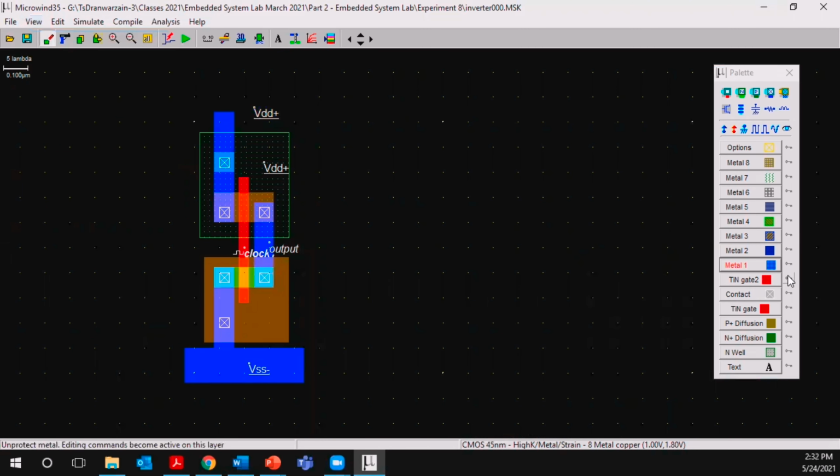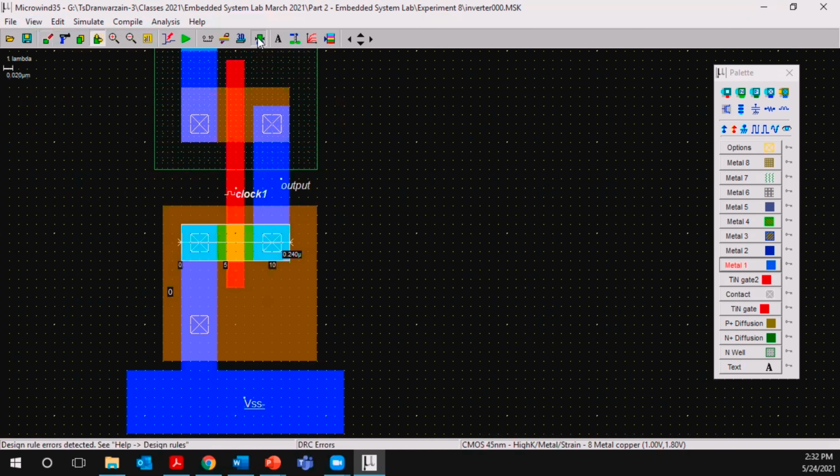All right. So we need to add one more time the VDD. Sometimes you will see the error, right? But now I want to create an error, but still no error. Wait, so maybe you can try this one. See, there is an error over here. So what does the error say? So that means this area should be less than 0.24.